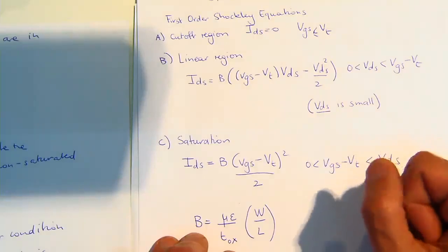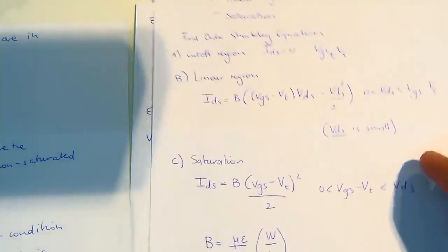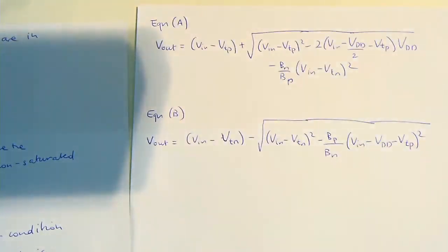Mu is different, right? Okay. So would you expect mu for the NMOS to be higher or lower? Higher, yes. Why? I got myself into a bit of a muddle last time. I was going to say, oh, because they weigh less, but it's not actually that. The mobility of holes is a lot less, probably about half that of electrons.